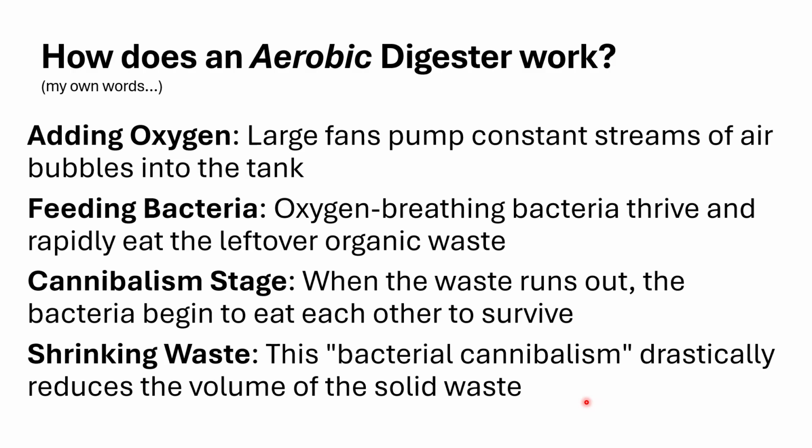So it's like the whole life process here, okay? I had a professor in civil engineering once who taught wastewater treatment, and he had a little curve that showed this perfectly. I'll see if I can find it and post it for you. But he talked about, okay, here's our microbial colony starting out. We're introducing sludge and oxygen and water, and here's what's happening. The population starts climbing, goes almost exponential, but the food dies out, and then the bacteria population stabilizes. Then it starts dipping because of this cannibalism, okay? So that's basically how the aerobic digester works.